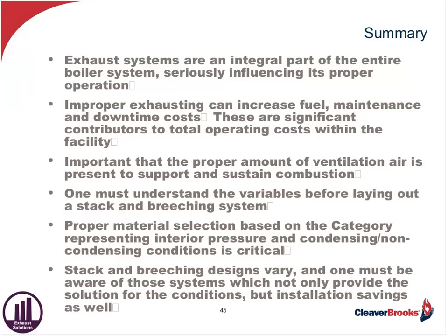All right, next question. There's an understanding of the need for adequate combustion air, but how do you calculate the free area? How do you handle cold air temperatures entering the boiler room? Well, as I mentioned before, as far as the free area is concerned, you use 10 CFM per boiler horsepower, and depending upon the height of the ceiling in the boiler room itself, 7 feet, you would divide by 250.